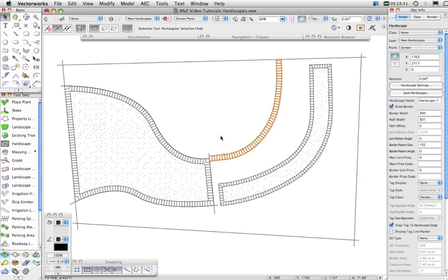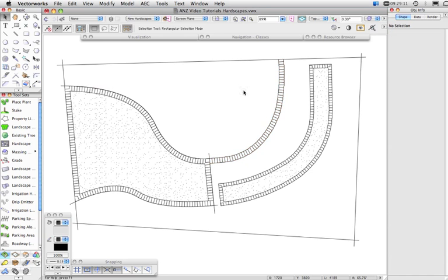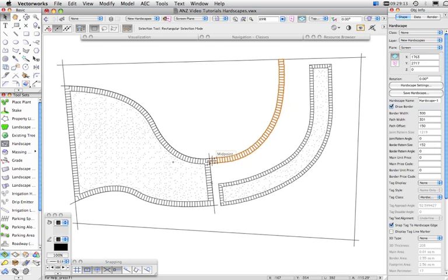Now you'll notice that it created this edging here along the center line of that polyline that was previously there. Now that's okay. I could have made that adjustment in the settings dialog a moment ago, but the path offset is also here, and so I can just set that to 150, and that's just going to offset the path so that it's based along that edge. Alright, so that gets me this edging here, and so on. So I'm getting close to what I need.